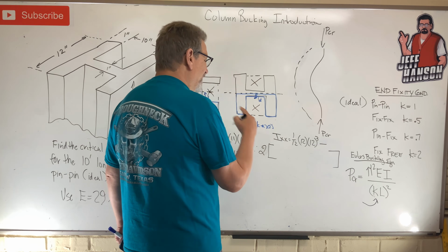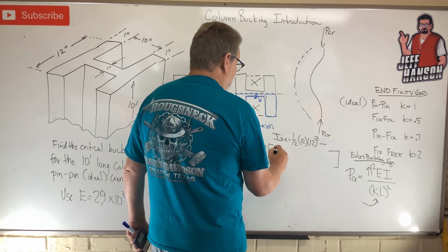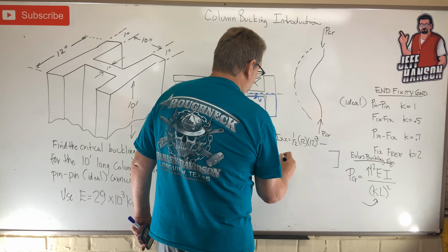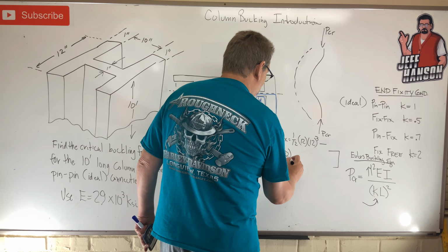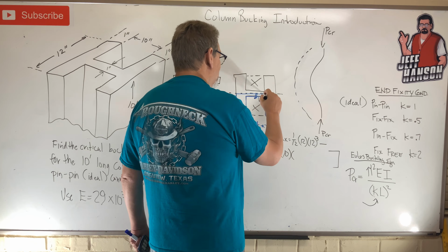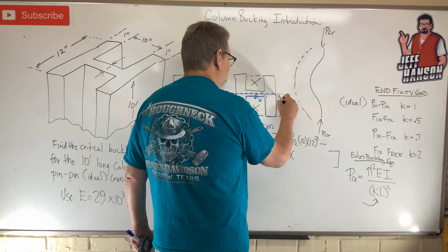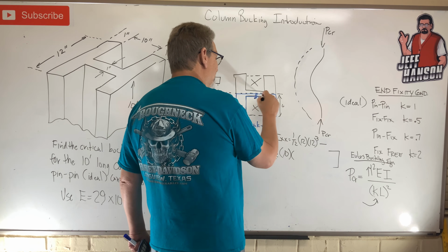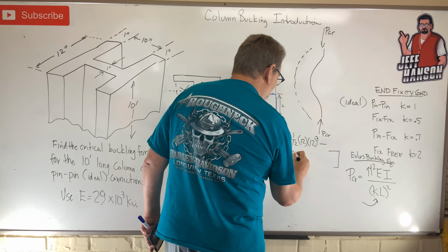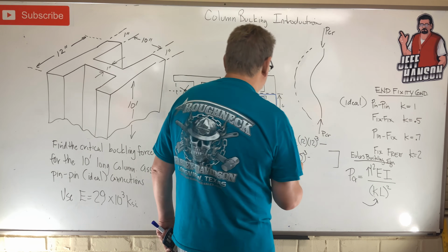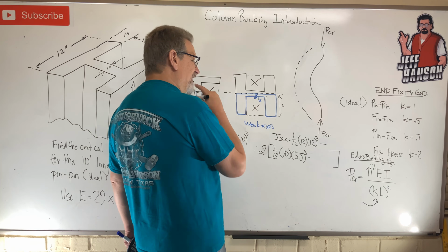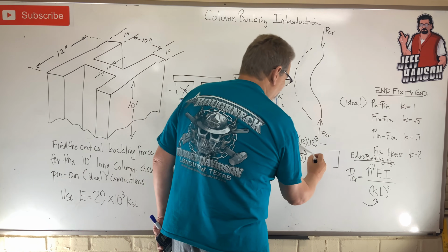And here we go. One of those guys is this: 1/12, the base is 10, the height is, let's see, this height here is 6. That's 1, so that's a half. So the height is 5.5. BH cubed minus A, that area, 5.5 times 10, that's 55.